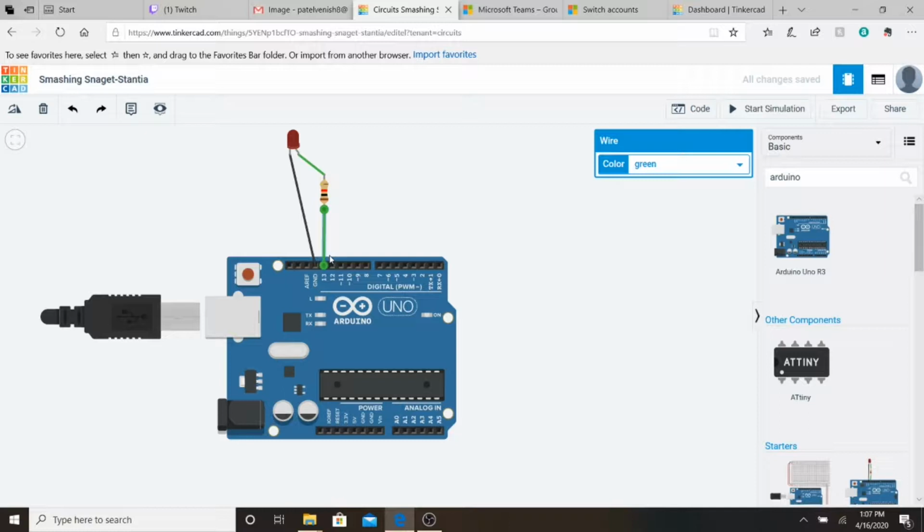It really doesn't matter if the resistor comes after or before the LED, or which way round it goes. The colored strips here indicate the resistor's values, and for this circuit, anything from 100 to 1000 ohms will work great. Here we can set how much resistance we want and the color will change accordingly.